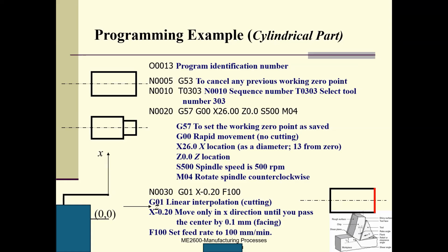But it depends on the sophistication, the complexity of your machine system, and some functionalities this machine does not have. So if you had a function that wasn't in the standard code, you would just do an M and your own number, and you just have to specify what that does. Yes, that is what the CAM does.